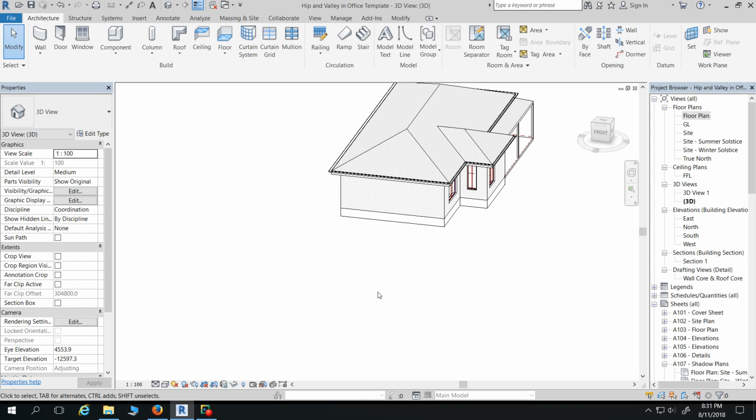You can do the same again for your gutter, but you've got to do your gutter like there, all the points, because it doesn't recognise that as one thing, unfortunately. Why is that one? It shouldn't be. Just go edit footprint. Edit footprint again. Just double check that that is the same as that. That the overhang is the same, and the pitch is the same, and all that stuff.